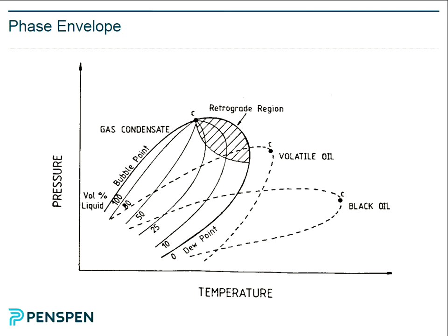And then there's this term API gravity. API gravity you can relate directly to density, basically. For volatile oil it's an API gravity which is greater than 40. So the higher the API gravity, the lighter the density, basically. The fewer the heavier hydrocarbons, basically. Colour of the stock tank liquid: black, orange or green. Light, relatively inviscid, I would say. Then black oil itself, not much gas, less than 2,000 standard cubic feet per stock tank barrel, less than 40 API.